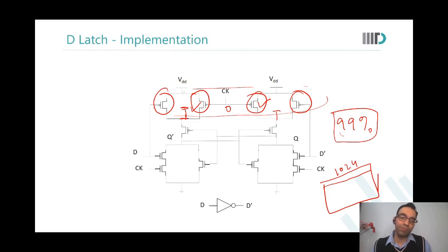Yeah. So you tell me, if I do not use a full CMOS circuit, what do? We have already done some such circuits where we were not using full CMOS. So what were the constraints that were coming on our way? Like we can use a domino logic or something. Okay. We do not want to make a DRAM. We want to use static logic only. So what was the static method in which we were not using the PMOS stack, or not using as many PMOSes? We were using the pseudo-NMOS.